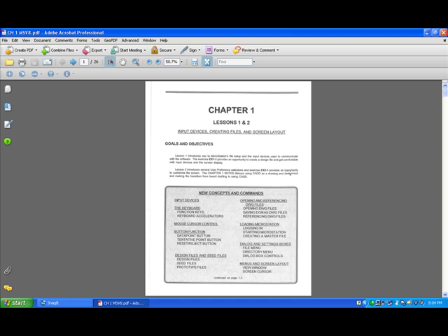Opening and referencing DWG files, it can be done. DWG is the native file of Autocad. We can open and close those, work with them directly in Microstation, so there's no difference there. We're going to talk about referencing. If you're familiar with Autocad, they have a term called X-refing, or X-referencing, being able to bring another drawing into this drawing, reading it in without actually having to redraw it or copy it into the folder. And then talking about file menus, menu directories, and the view windows.